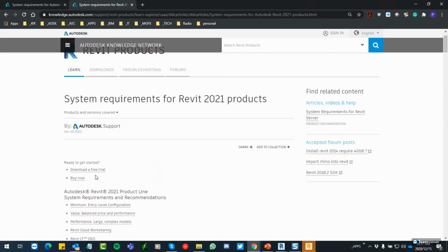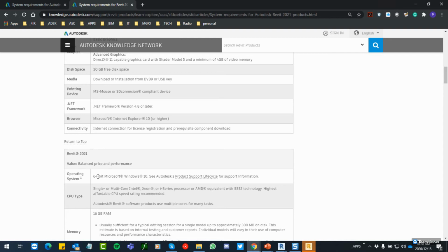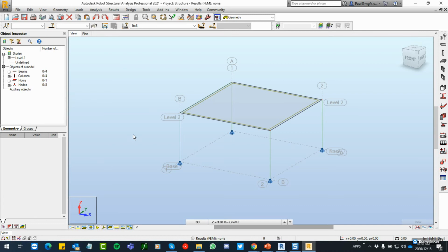So if you are going to be doing automation using Dynamo, then I would go so far as to say forget the 32, go for 64. If you are going to get into automation, then even go with 128 because Dynamo uses only RAM. That's what it uses. But it's not going to be an issue in this case. So 32 would be perfect. I agree with that. And also Revit loves fast processors. So you'll find that typically when you're working with Revit that it won't use multi-core processing, only when you render, but it loves very fast processors. So the faster your processor is, the better for Revit. And that will make it into a nice responsive computer and also solid state M.2 hard drive. So all of those things come into play.